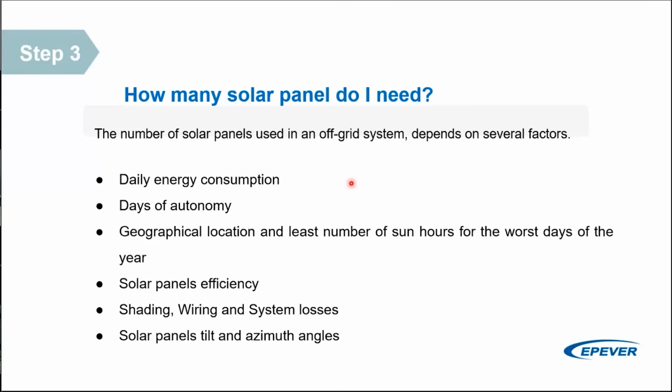This is called the open circuit voltage of the PV array. ISC, or short circuit current, occurs when the positive and negative leads are connected directly to each other, resulting in the highest current that the array can produce.